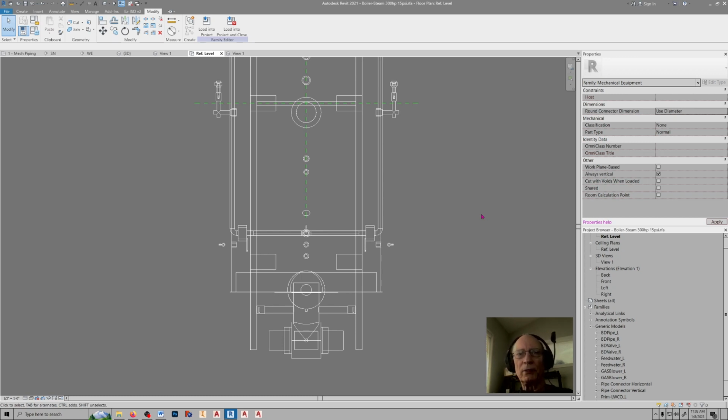The second is creating some parameters in the base family. That's your base equipment. One group is for the diameters of the nested family POCs, and the second group is for the visibility options. You also need to go into the family category and parameters tab and set the family filter list to mechanical and mechanical equipment. If you don't, your equipment's going to come in your project as a wireframe.